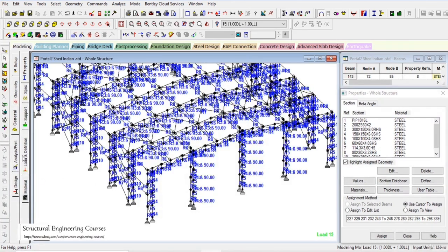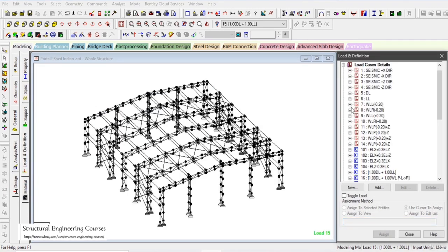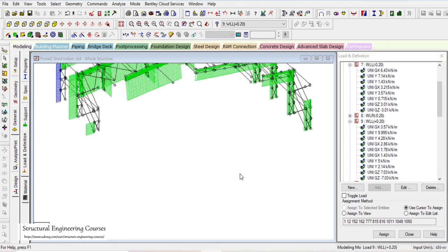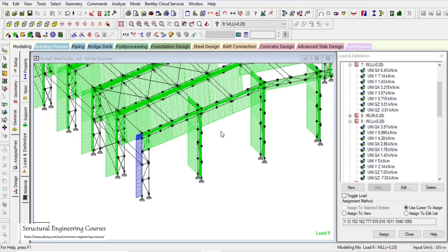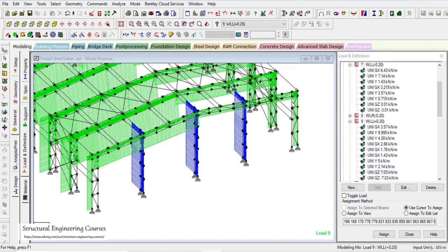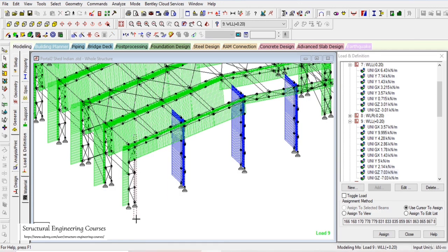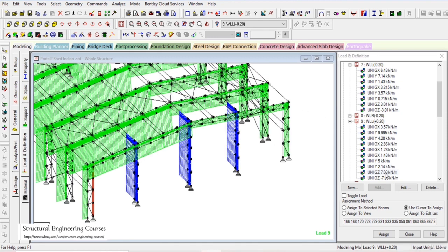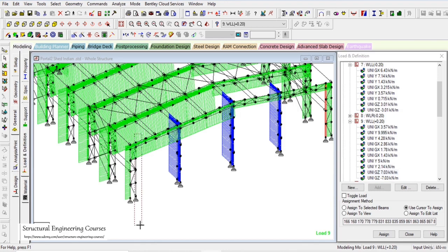And there's one more thing that I was just thinking about, that you should also know. When we are applying this loading here, the gable end forces are 7.03 kilonewton meter. 50% needs to be applied on these members also. So that I had missed in the initial analysis, but I am just saying this for your records, that you should not do anything incorrectly. That the 7.03 divided by 2, that is approximately 3.515 kilonewton per meter UDL shall be applied on this column here and this column here also.